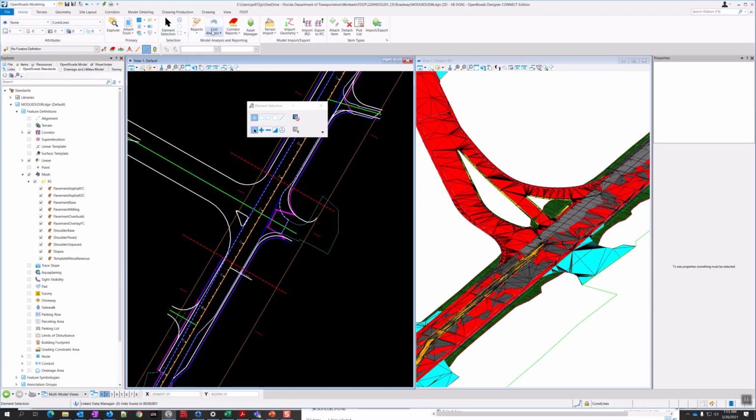Alright, so I come to the same place over here, and I'm just going to hit the button again because it's the same tool. Civil analysis, create cut fill volumes. So same, accepting the defaults. Just accept all of those. Data point.